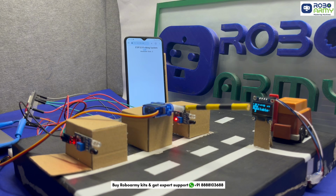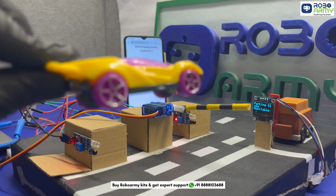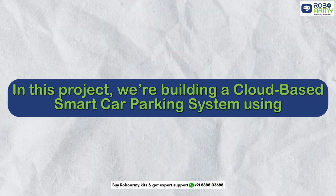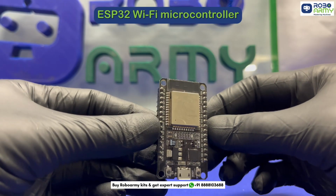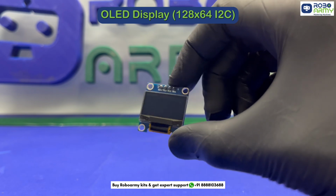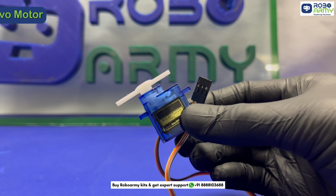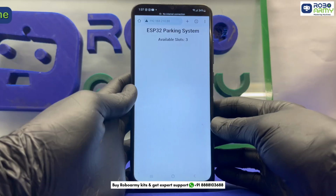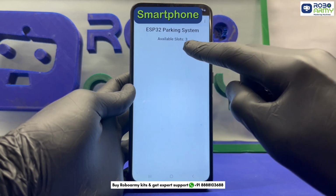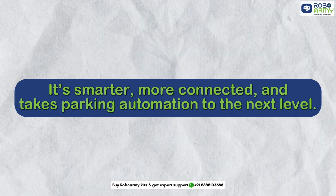But today, we are taking that project a step further, making it cloud-based using an ESP32 and OLED display for a better visual output. In this project, we are building a cloud-based smart car parking system using an ESP32 Wi-Fi microcontroller, OLED display 128 by 64 I2C, 2 IR sensors for entry and exit detection, a servo motor to control the parking gate, some jumper wires, breadboard, USB cable, and a smartphone with a web interface to monitor available slots live. It's smarter, more connected, and takes parking automation to the next level.